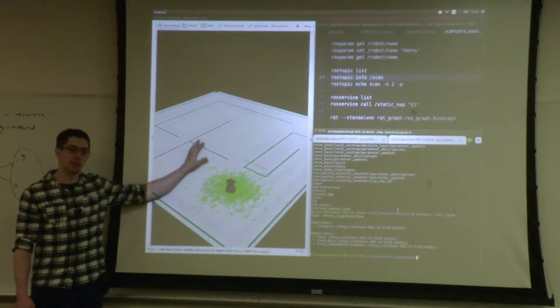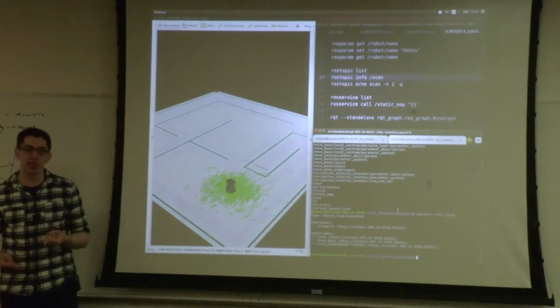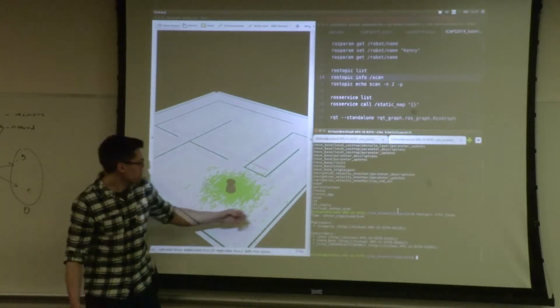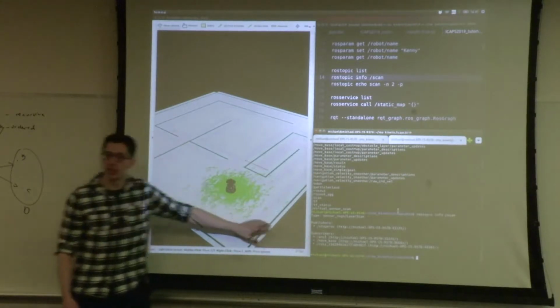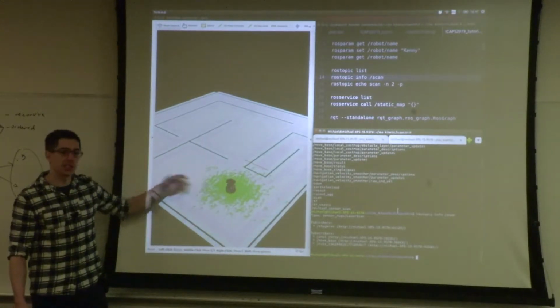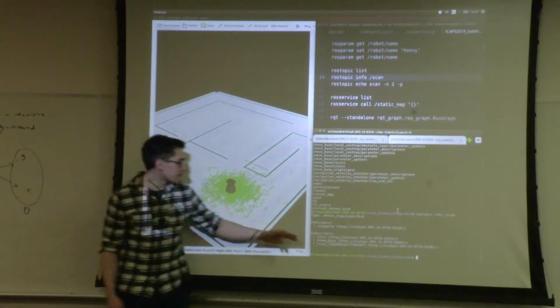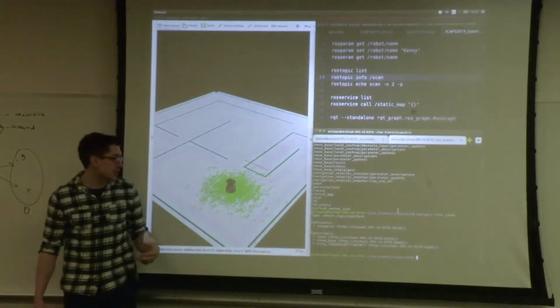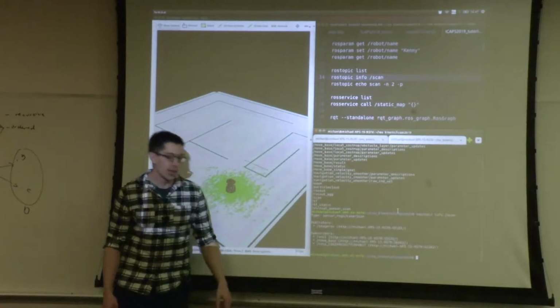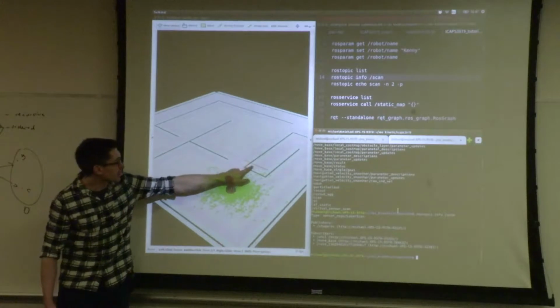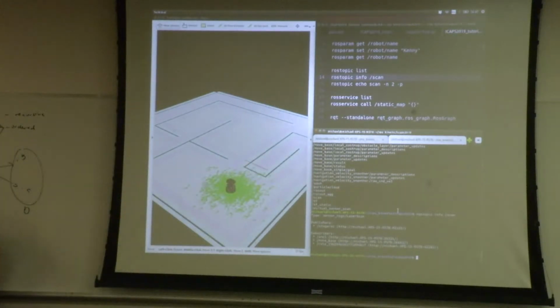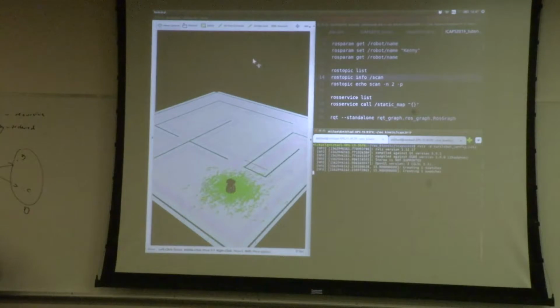This simulator is very simple. It doesn't actually simulate any physics. It's just simulating the sensor data. And it's subscribed to by AMCL, so that's the one that's performing this localization. It's listening to the scan to try and decide where the robot is. Also to MoveBase, which is the navigation component, so that's the collision avoidance. And finally, it's being subscribed to by RViz, which is this visualizer. You see this red line is actually the scan topic. I think if I give it a little movement, then you'll see the red line moves as the robot does.